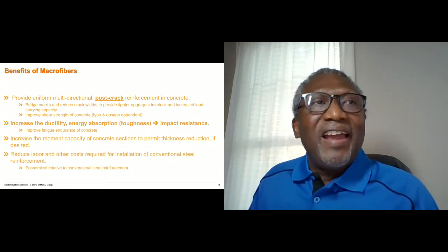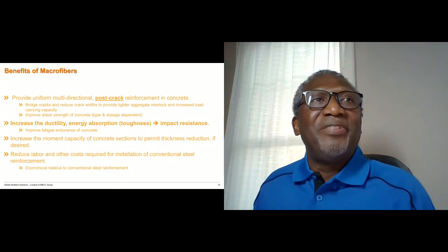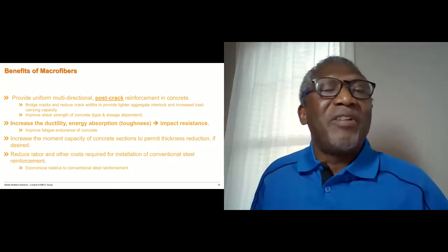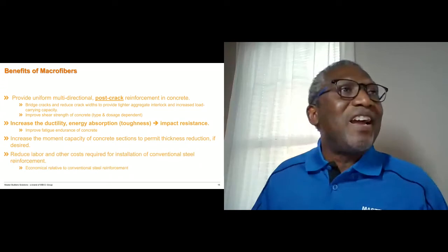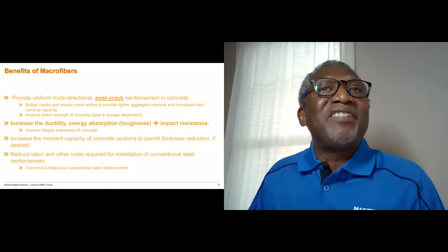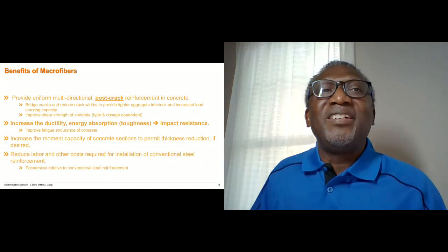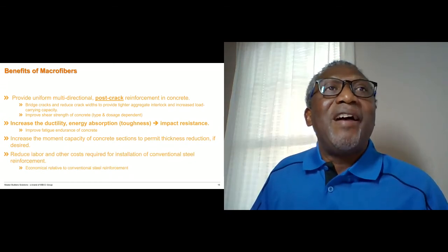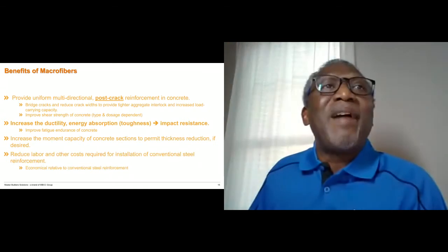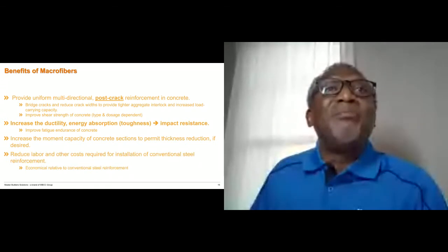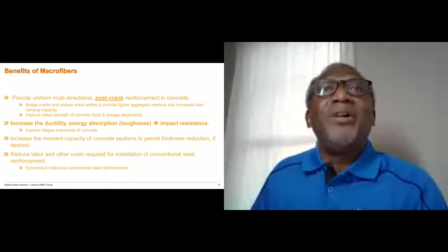Now, this next slide basically has three different videos that show the impact resistance of concrete. The first section was a non-reinforced slab, and after 2 blows of the sledgehammer, it essentially broke apart. The middle slab, reinforced with 6x6 W2.9 by W2.9, as you can see here, was broken after 11 blows.